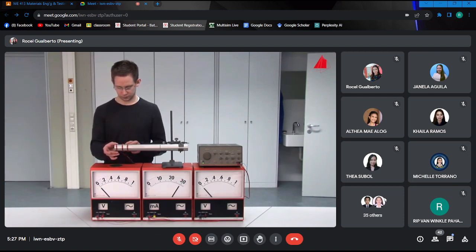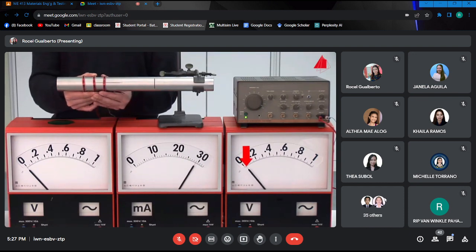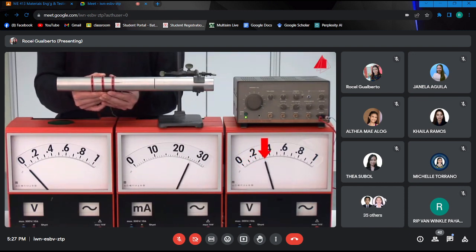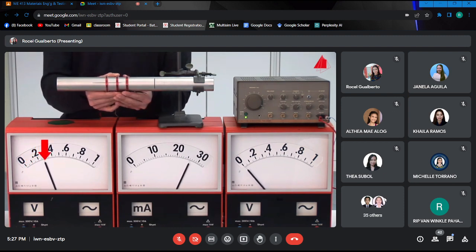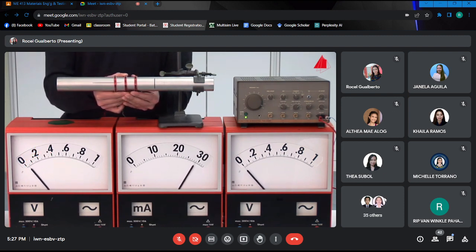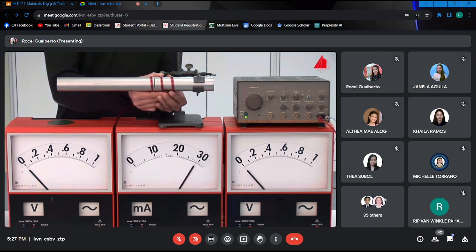Last in turn is the left receiver coil. He carefully takes all 3 coils and moves them to the right. The pointer of the right voltage meter deflects, then the pointer of the left voltage meter. Further to the right, where the tube is intact, the pointers of none of the voltage meters are deflected. Unfortunately, the saw cut in circumferential direction is again not detectable.